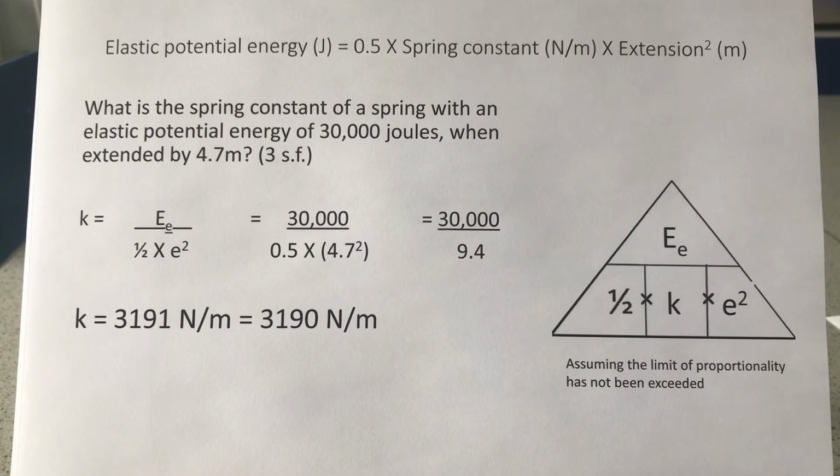So you stretch an elastic band and it stretches in this uniform way, this way that kind of gives us this positive correlation on a graph. And then after a while you keep pulling it and you put more and more force into it, but it doesn't stretch anymore. Okay, where that graph kind of tails off and it stops being a straight line graph, kind of curves off at the top, we've reached the limit of proportionality. So all of this calculation is used within that limit of proportionality. So spring constant kind of gives us an indication of how stretchy a spring or an elastic band is.